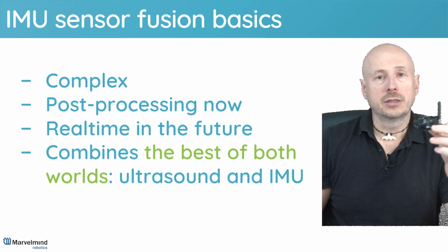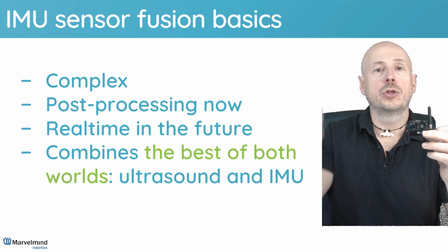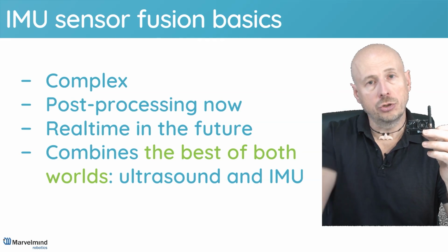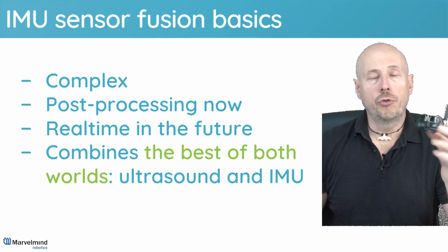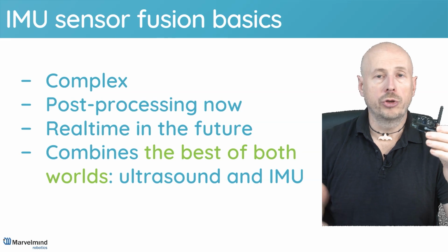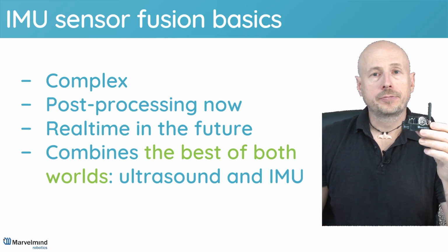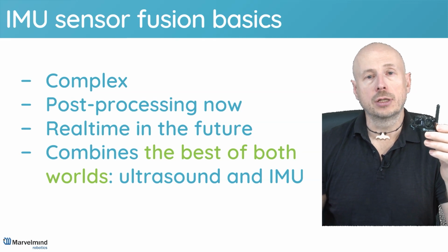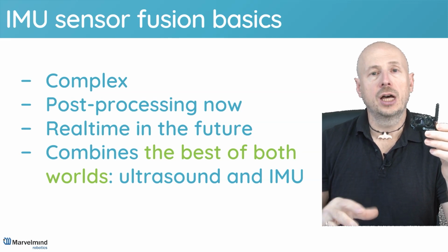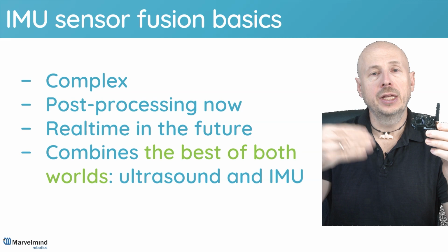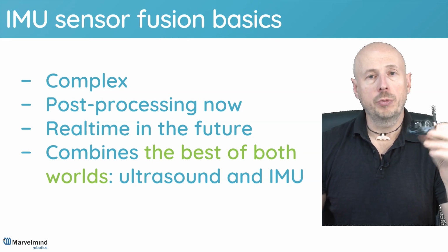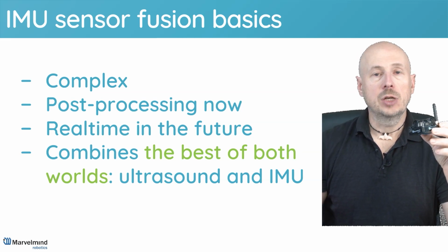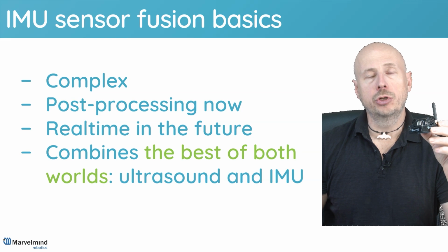will again correct it. And ultrasound corrects the drift, because there is all the time drifts of IMU, both accelerometer and gyroscope. But it does it a few times per second, and to get the location data from the double integration of the accelerometer data, which is all the time corrected by the ultrasound data.